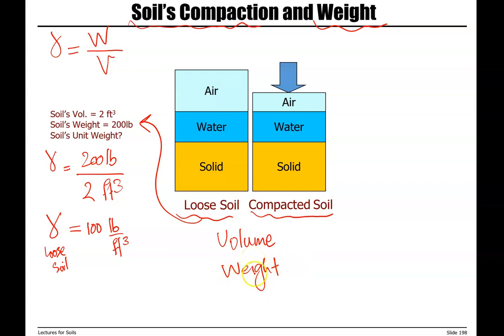So we still have the same weight, which is 200 pounds, but we observe a decrease in the volume of our soil sample. Volume is decreased from 2 cubic feet to 1.5 cubic feet.